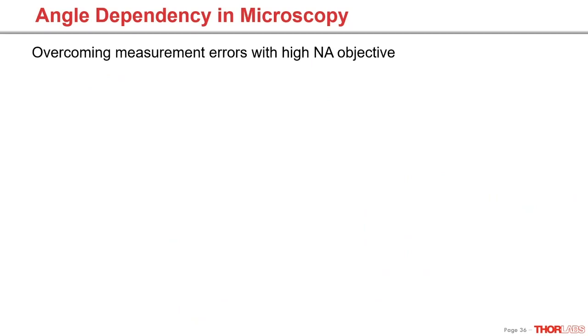Let's have a closer look at a specific application: power measurement at a microscope, especially if you want to measure the power at the objective plane. Here, usually the light is strongly divergent, given by the high NA of the objective. A warning ahead: don't focus on the active area of the photodiode when measuring the power at that spot. The diode could take damage from the high power density. Integrating sphere or standard thermal sensors are usually ruled out for reasons of space.